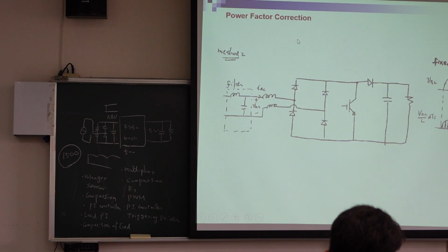If dI/dt is positive, how about I(t)? I(t) is I0 plus (VG/2L) multiplied by delta T, right? You can solve this equation easily. So what is your current? If you have positive voltage, your current could be like this.